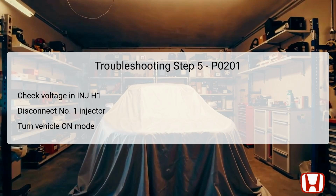This check allows you to see if there's any unintended voltage present that might indicate a short to power within the INJH1 wire. If you observe a voltage reading, this means further action is essential, specifically to repair the short to power located in the INJH1 wire between the specified connectors. If no voltage is indicated, then proceed to step 6 for further diagnostics.